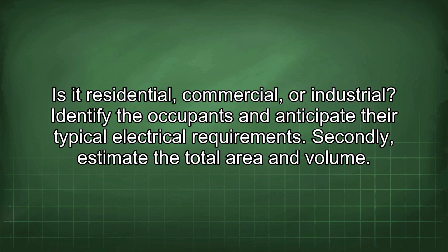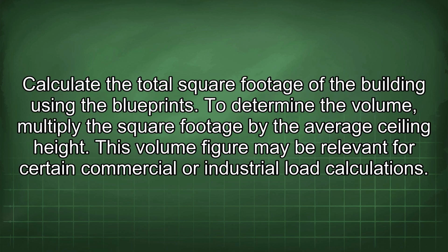Secondly, estimate the total area and volume. Calculate the total square footage of the building using the blueprints. To determine the volume, multiply the square footage by the average ceiling height. This volume figure may be relevant for certain commercial or industrial load calculations.